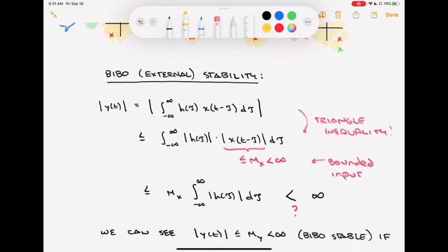We also had talked, and this was back in chapter 1, about the external stability measure, this idea of bounded input, bounded output stability. My guess is that most people really didn't like trying to find ways to demonstrate a system was BIBO or externally stable. That wasn't necessarily a very simple process. You needed to do some thinking about the system, and you didn't necessarily have a straightforward single one-size-fits-all way of demonstrating that. In the case that we have these linear time invariant continuous systems described by constant coefficient linear differential equations, for which we know that we have an impulse response, and that impulse response captures the character of the system, we can end up determining BIBO stability in a very straightforward procedure.